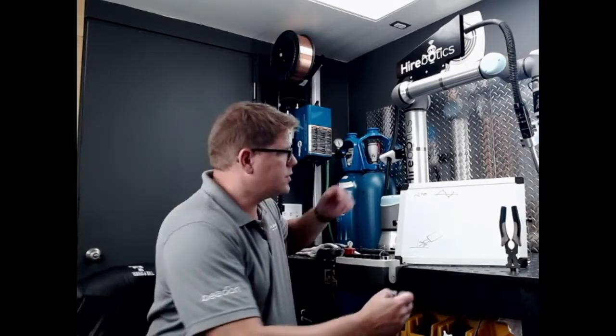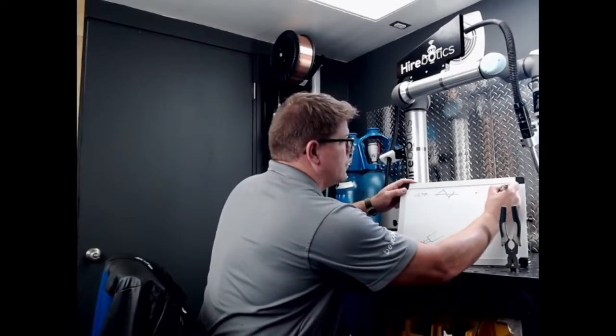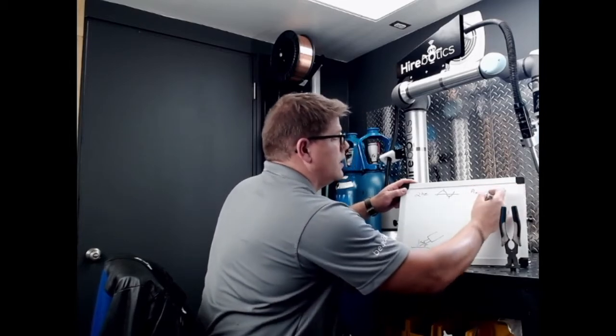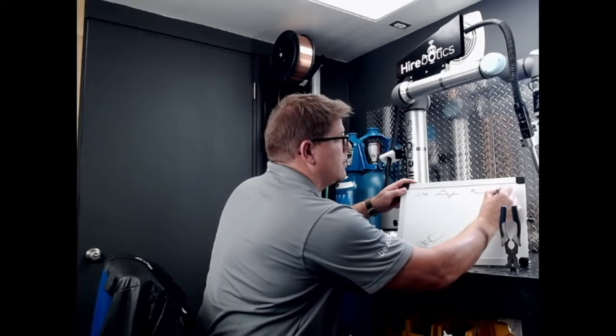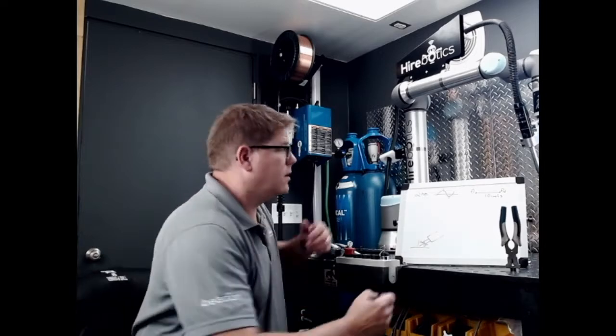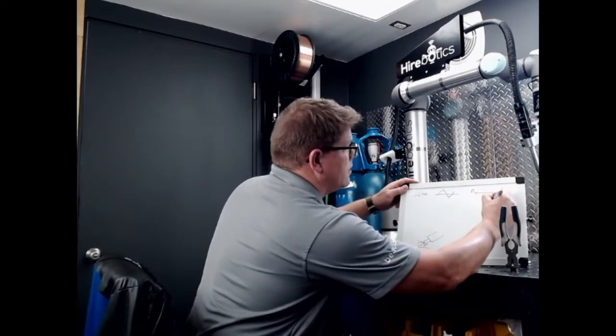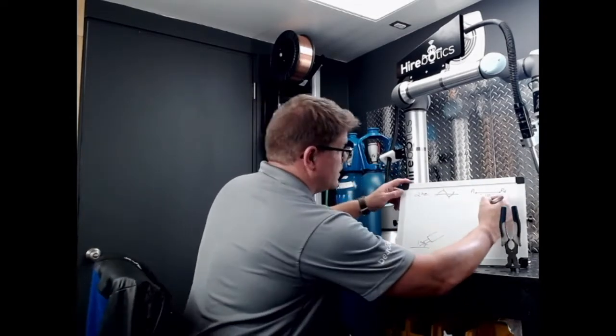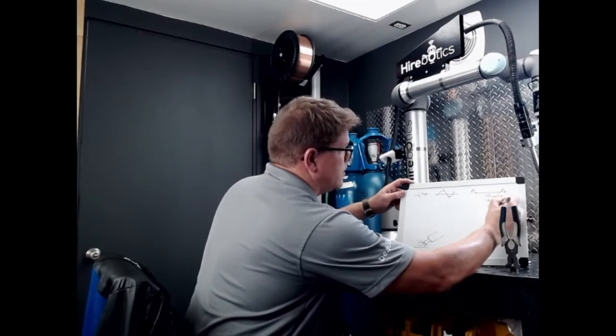The amount of time that's going to determine the number of peak to peaks is a function of your travel speed and distance of your weld. So let's just say you have a fixed weld distance. Your fixed weld distance, P1 and P2, is 10 inches. If you set a travel speed of 10 inches per minute, it's going to take you 60 seconds, 1 minute, to make that weld.